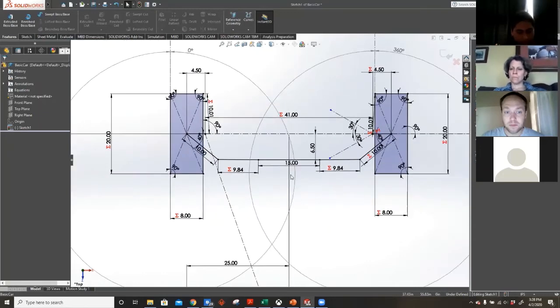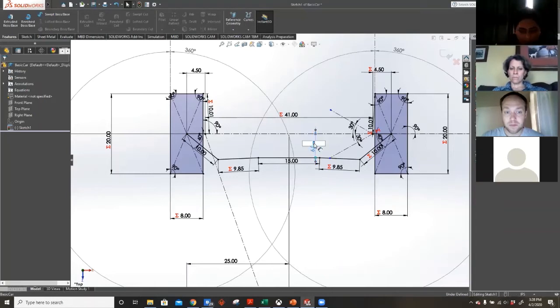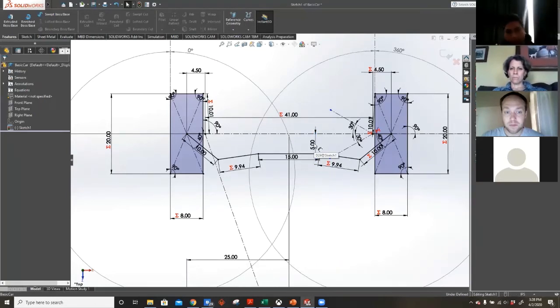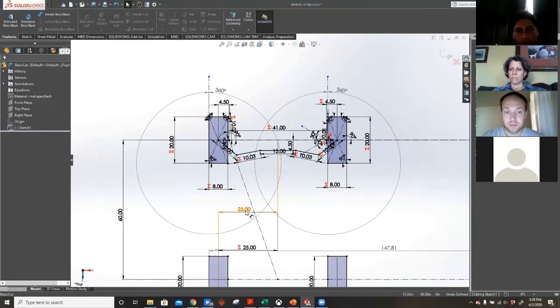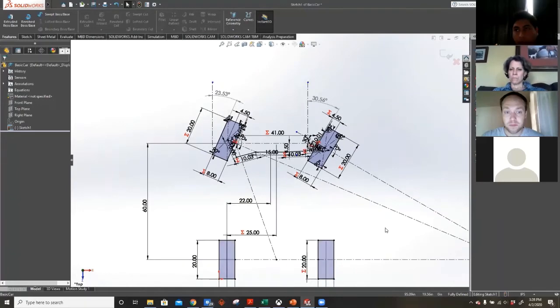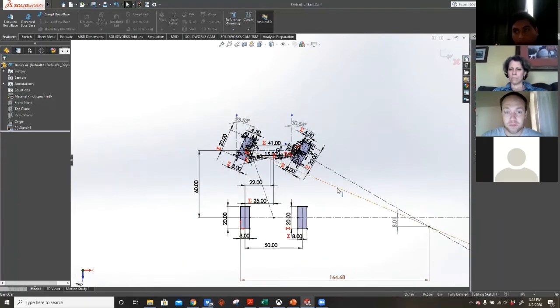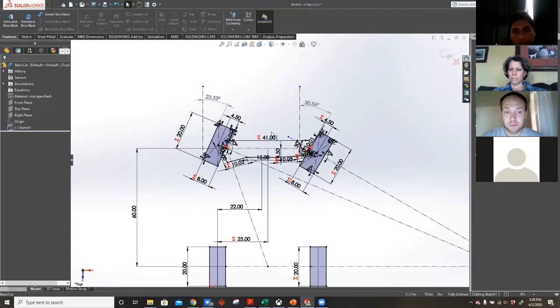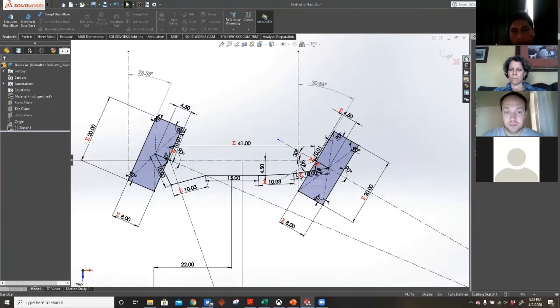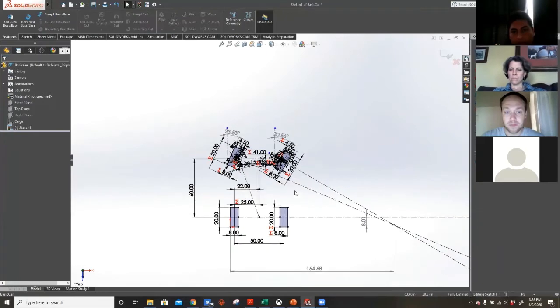Maybe move your rack up too, a little bit. Part of the problem is that your tie rods are almost at the same angle as your steering arm. Moving that up, see what that does. Let's try that. See if it still goes to 22. Let's see what your turning radius is. That's a little lower actually, about 20 inches lower. There you go, and you're within the 1 foot now. So let's try something else. Try going 20, put it back straight.